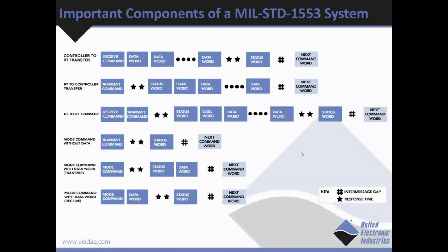Messages on the bus can take several forms. A BC to RT command sends data to a remote terminal subaddress. For instance, the mission computer may have to send a firing command to a missile. An RT to BC command asks the RTSA to send data to the mission computer. For instance, that might be airspeed or temperature data that the mission computer needs.